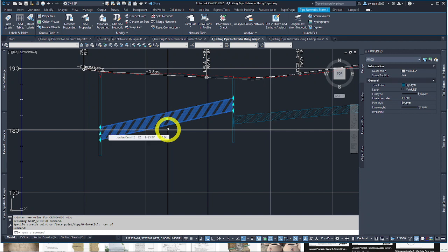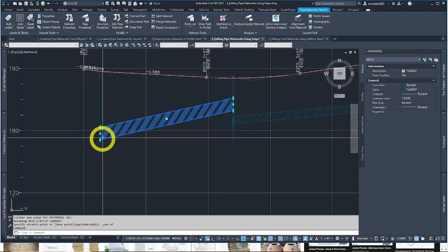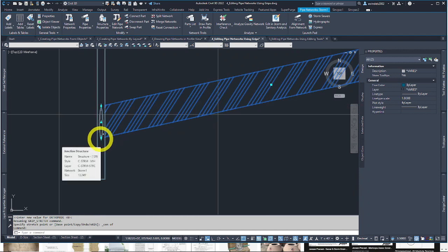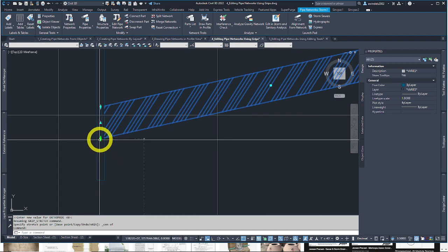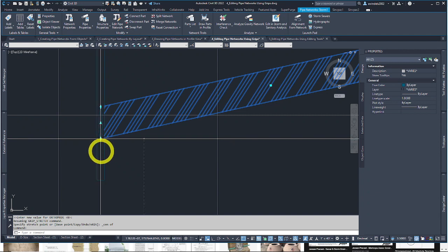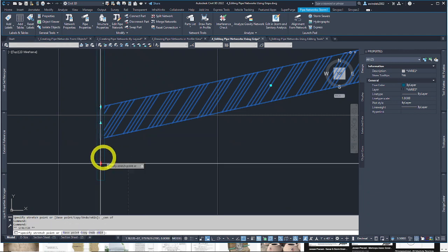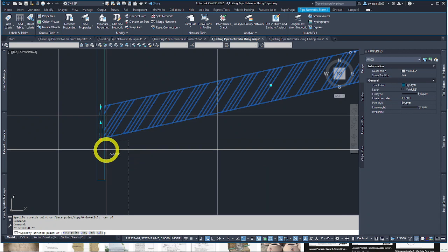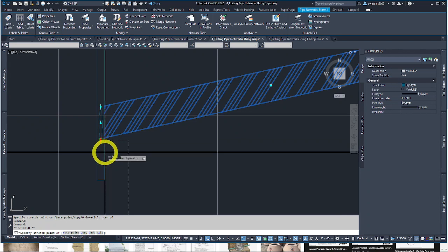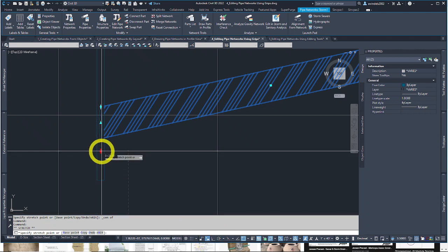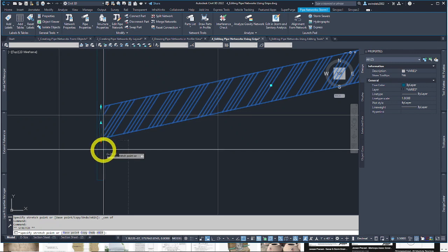We're going to pick the bottom diamond-shaped grip on the left side of the pipe, which is here. Okay. Hover close to it. That helps. I'm having a little issue of AutoCAD recognizing it quickly. Hover on it. Pull that down. You can pick it somewhere graphically, or since I'm moving it, and we have to have dynamic input on, which we do, you can type in 180. See if that worked. Type it in here in the command box.